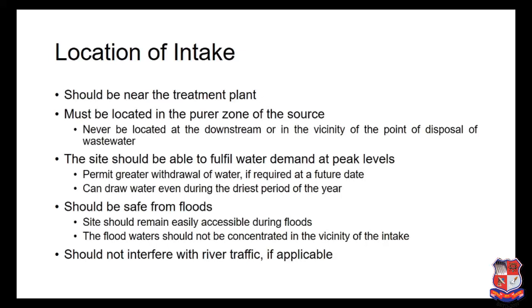So where should we provide the intake, or how can we select the site or the location of the intake? First, it should be very near to the treatment plant, right? If it is far from the treatment plant, then we have to pump the water for a further distance, and the energy cost for pumping will be more, and also the pipeline cost will be more. So it should be nearer to the treatment plant.